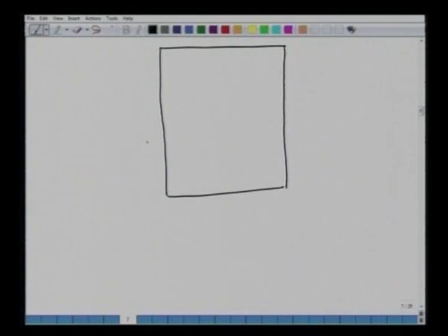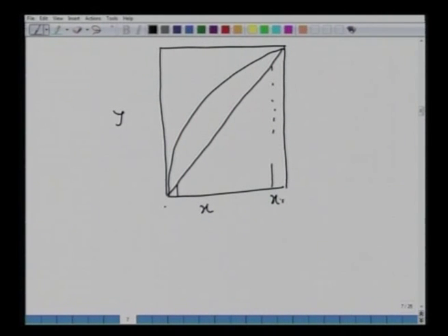So we will draw again this y versus x curve. Every time we have this McCabe-Thiele method, we have y versus x, unlike in the Ponchon-Savarit method, where we had the hx, yx diagram. So we have xt here and we have xw. We draw two operating lines anywhere; the q line will be fixed.